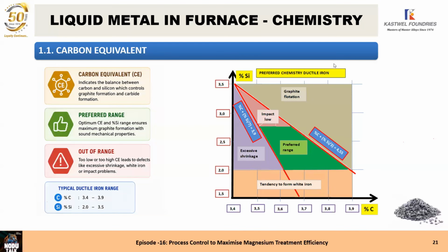Okay. Then you explained the 4 types of treatment in the magnesium. One is the open ladle treatment, that is very much inefficient, then the sandwich method. Third one, the tundish cover with the ladle, and fourth is the wire treatment. We have experienced both the sandwich and tundish ladle cover treatment.